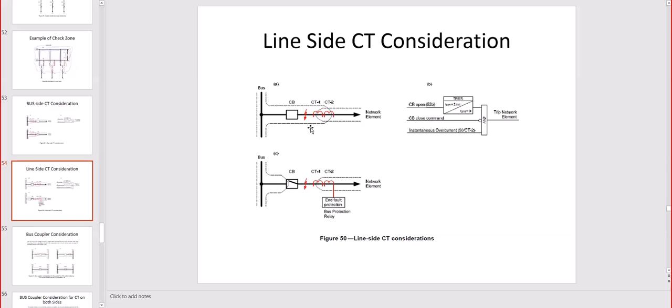The other way to read the breaker health is via currents. That's why is another reason that we have the CT on both sides of the breaker. If you claim that the breaker is closed on all three phases, you should read the current on all three phases on both sides. If one side doesn't read that, then you have a problem.